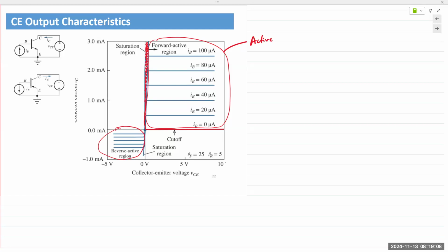At this point, I'd like to remind you that FETs and MOSFETs are theoretically symmetrical devices, so the drain and the source can be interchanged and would still work. BJTs are not. By its very fabrication, the BJT is not a symmetrical device. The emitter is very heavily doped and a very small structure. The collector is the largest structure, but it's the lightest doped of all three. The base is very, very thin. So if we interchange the terminals, it's not going to work for that very reason.